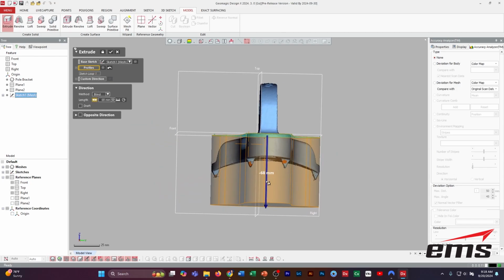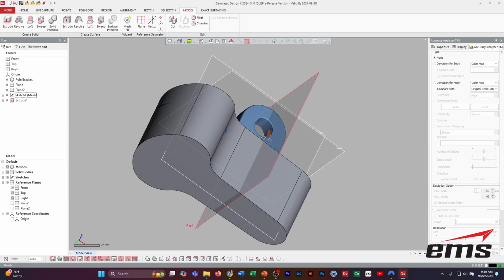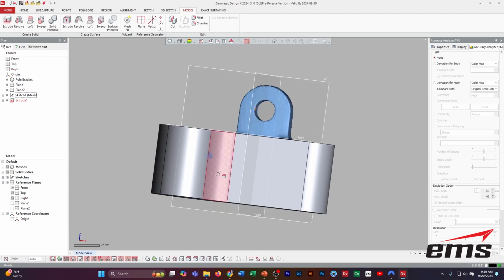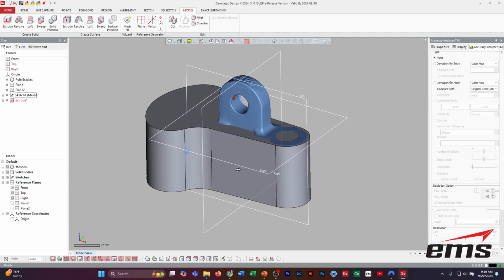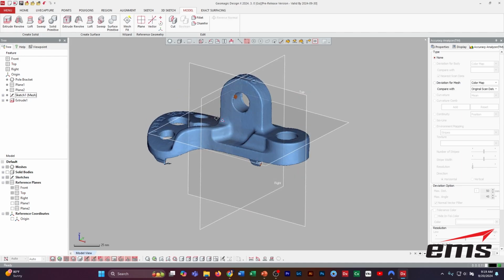But you can see because this has curvature to it, when we do a blind extrusion, and your extrusions are all the common ones: blind, up to a surface, up to a region, I'll explain region in a minute, up to a body or mid plane. We're just doing a blind. We're just going to go down some value, okay? Because we can't extrude it to a curve, okay? Now we're going to do that essentially in a second. Now let's go ahead and hide that for a minute. So we've got that established.